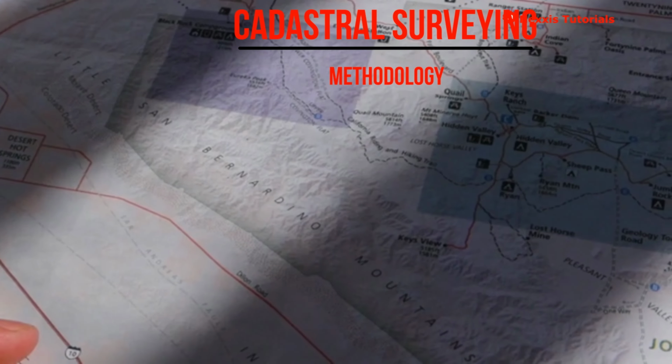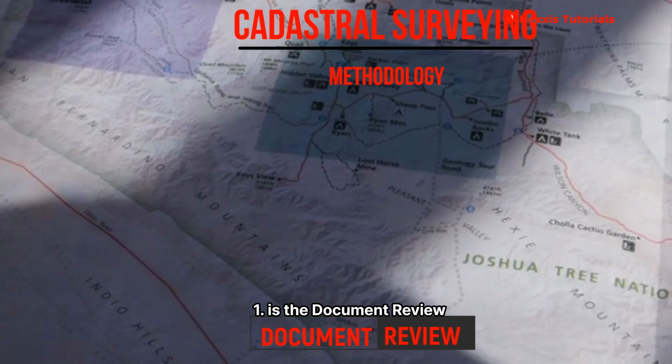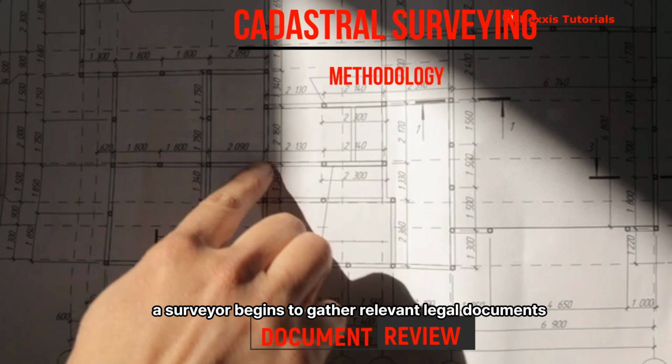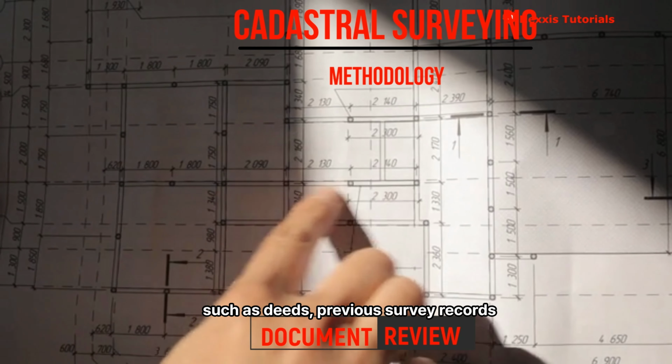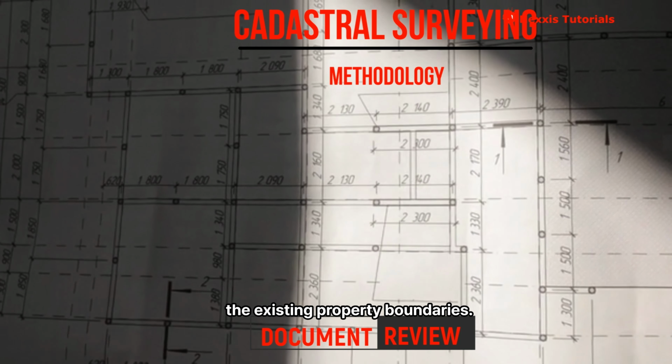Cadastral surveying typically follows a systematic approach. 1 is the document review. The surveyor begins to gather relevant legal documents such as deeds, previous survey records, and municipal maps to understand the existing property boundaries.